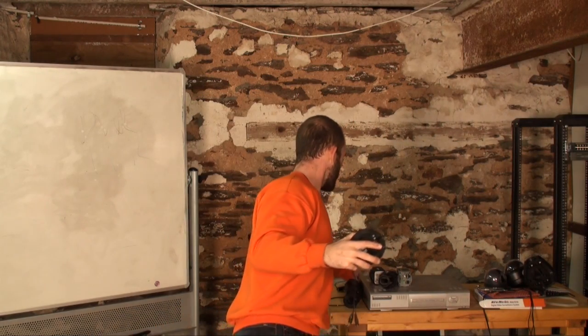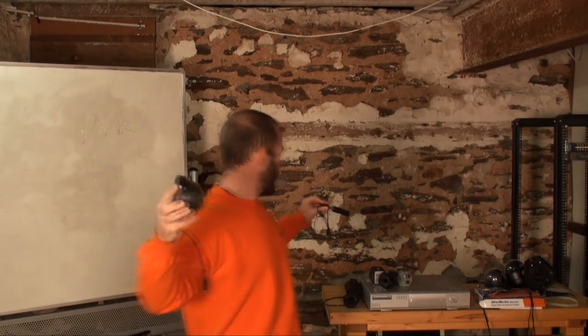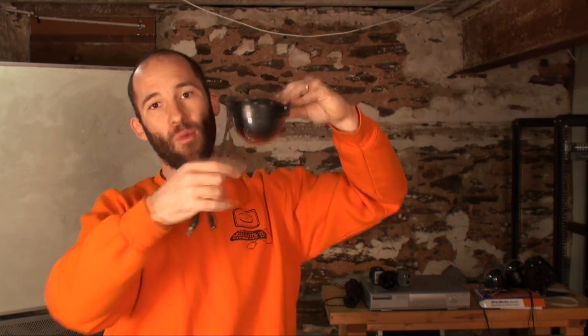The nice part why people like dome cameras is because once they're set up properly, you can't mess with it. With a bullet camera, the nice part is you just screw it to the wall, you aim it by moving it, and then you walk away. The problem is an employee or a criminal can also move it just by hitting it with something, and then it's no longer seeing what it's supposed to see. With a dome camera, the reason people use them is it's protected by the dome, so you can't just whack it. Once you've moved it to where it should be, it will always stay there.